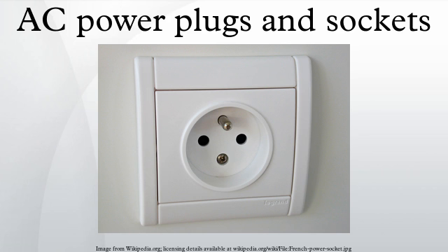CEE 7/5, Type E. French standard NF C 61-314, plugs and socket outlets for household and similar purposes, defines a round plug with two round pins measuring 4.8 by 19 mm, spaced 19 mm apart and with a hole for the socket's earth pin. This standard is also used in Belgium, Poland, the Czech Republic, Slovakia and some other countries. Although the plug is polarized, there is no universally observed standard for placement of the line and neutral. However, the Czech standard recommends the line wire to be on the left side when facing the socket.